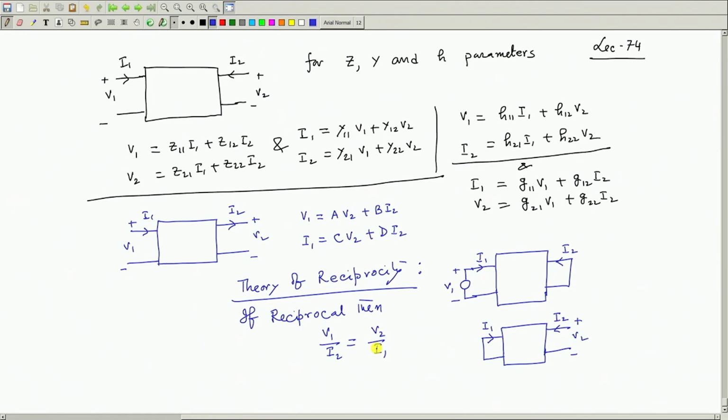It is always true. While describing the reciprocity theorem, from that we established this. Therefore, this ratio will be the same for a reciprocal network, which demands that the network elements should be linear like RLC, and also they should be bilateral. RLC are all bilateral, no diode present like that. So, if this is V2, then this will be I1, and you see V1 by I2, the sense of the current I1 is also the same, flowing this way. So, this is the thing that should be verified.